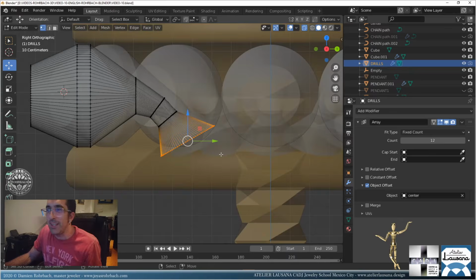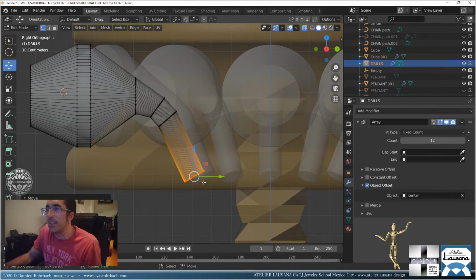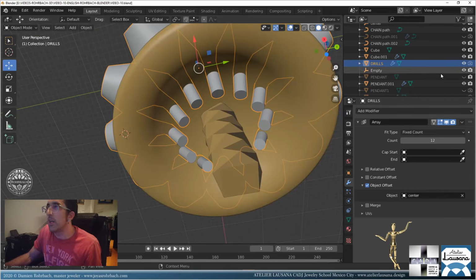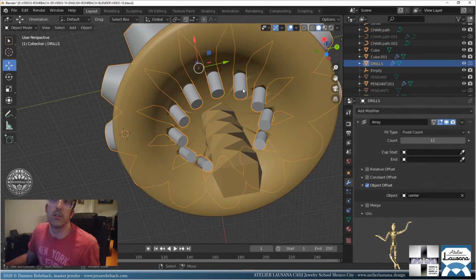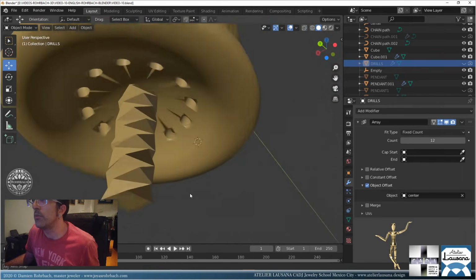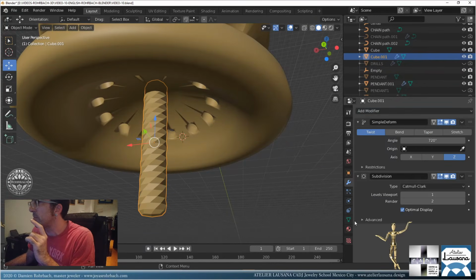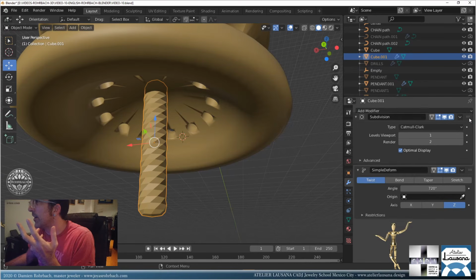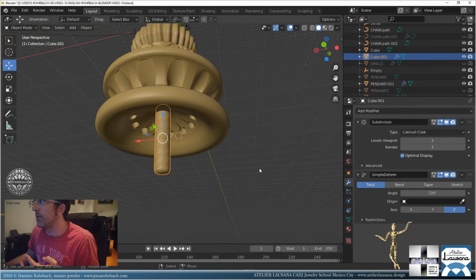Sometimes we can't, but here I can because the design on the inside is actually not so necessary, and the overlap might be killing the Boolean right there. Okay, now let's turn it back on here, show it, and let's wait a second. Take the drills, hide the drills. Problem solved. The Boolean is now perfect, and you can see this guy. Okay, so here, let's make it just so it looks nice. We won't even see this wire on the render.